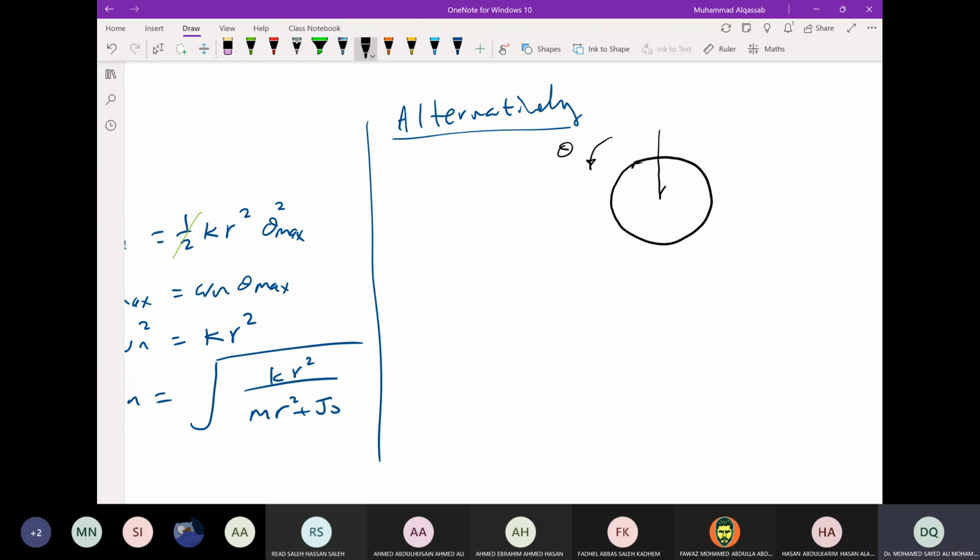I know that there is the weight, and there is the normal force. Okay, those things I know, and you know. What are the other forces? The spring force, right? The spring force is to the right. The reason is that with the assumption theta counterclockwise, the spring will be under tension. So it is pulling the cylinder to the right with force kx.